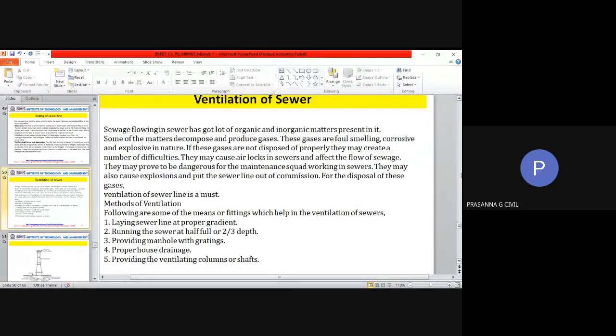Proper house drainage starts from your building itself. From your building, you have your individual house sewer connected to the one on the main road or lateral road. That will be called the lateral sewer line. So in your house, the small pipe carrying all the wastewater will be connected to the manhole on the lateral. The laterals can have manholes, the branch sewers will have manholes, and the main sewers will have manholes. The size of the manholes will again depend upon where that manhole is getting constructed.